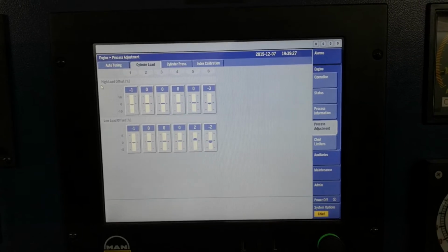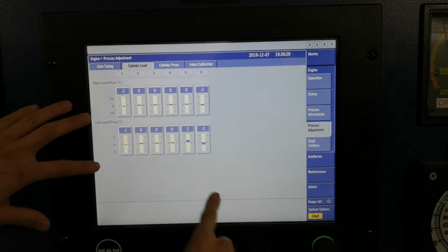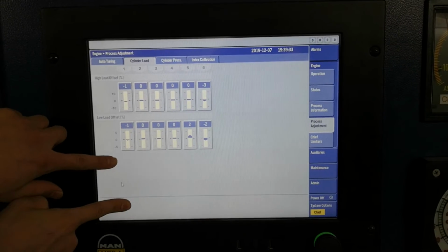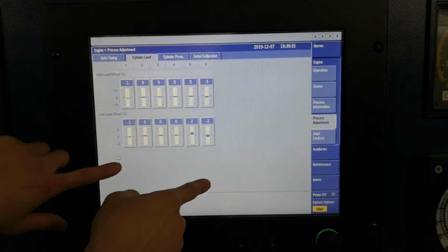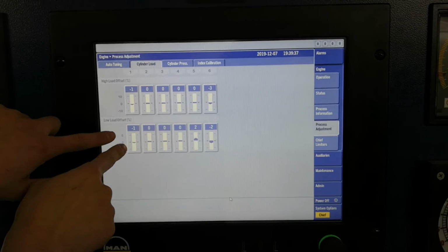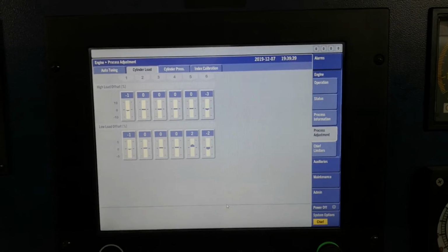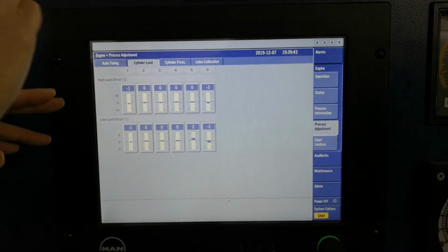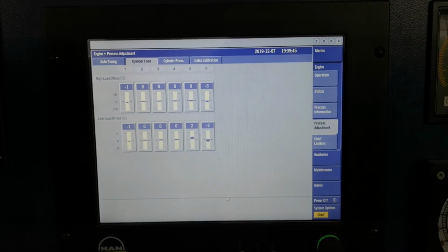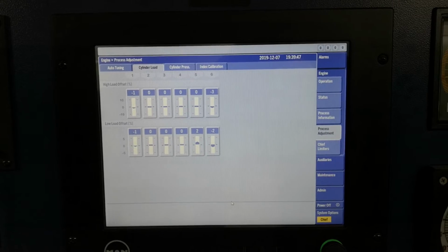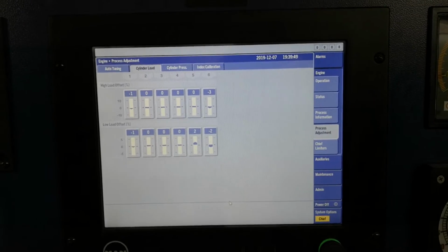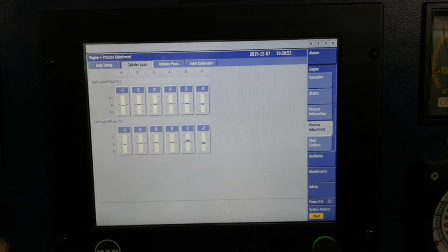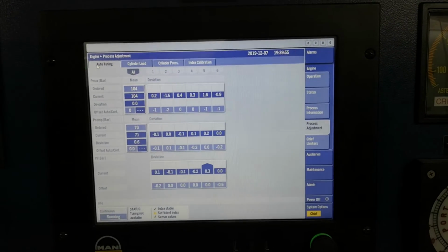The baseline between the low load and high load is 50. But at high load we have a graph here. At low load the offset affects a lot in proportion. But at high load, even if you adjust with small micro control, for example number 1 plus 3, there will be a lot of change in the gas temperature. At low load, just a small change. Of course, because on high load the injection has more fuel quantity.